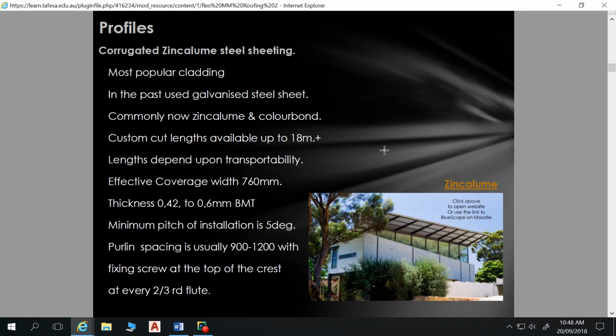If you're very good with your scribing, I guess you can close it up to several millimeters. You'll still need to use some foam behind that, or mineral fibre for bushfire prone areas, but it's a neater detail than the unscribed capping. When someone else is driving and you're having a look around at houses, have a look. Some you'll see are scribed, some you'll see are unscribed.